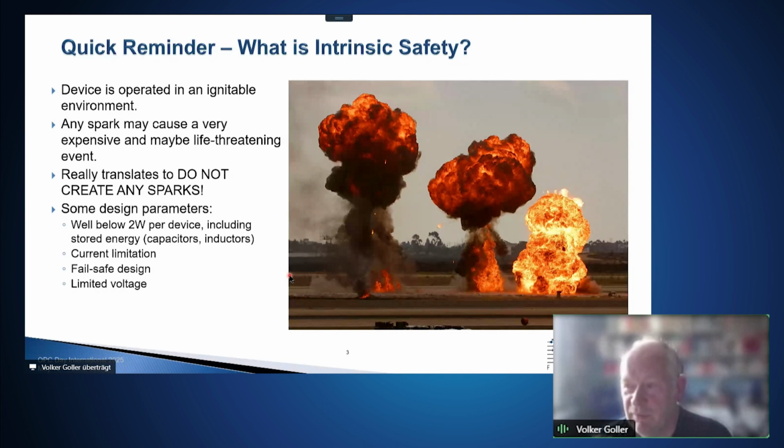So some of the device parameters that you have to cover for this: the power needs to be well below 2 watt per device. And that includes the stored energy. If you have a device, you power it up, there are capacitors and inductors, they store energy, and even if you pull the plug, there's still energy in the device.